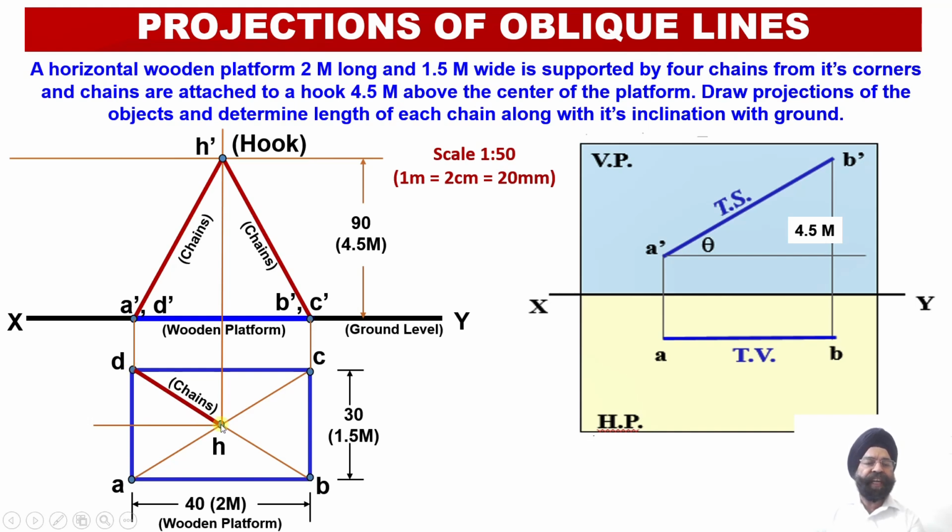So we'll keep the needle point of the compass at point H and rotate this line HD in such a way, open the compass equal to HD distance, rotate point D and extend this curve up to the horizontal locus line which is emerging from the point H, and once this curve intersects with this horizontal locus line passing through the point H, this point of intersection, because this is the first rotation, will be named D1.